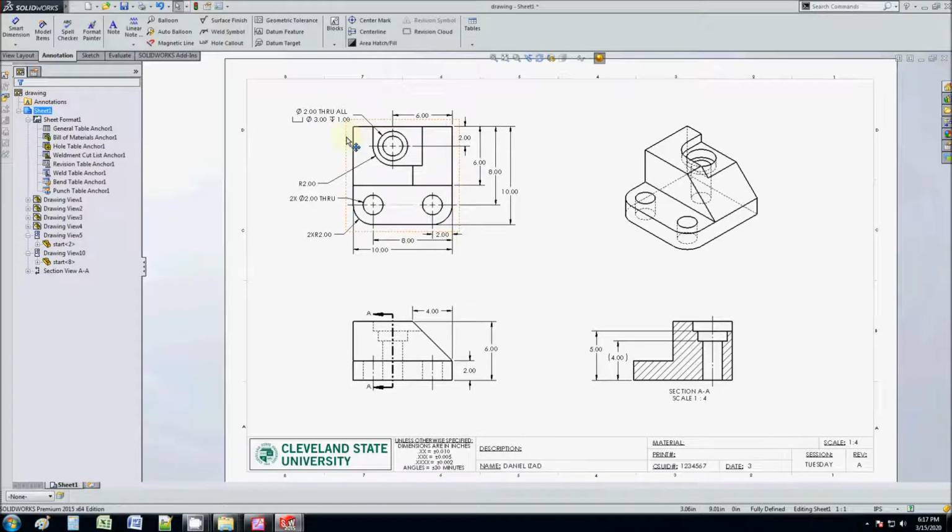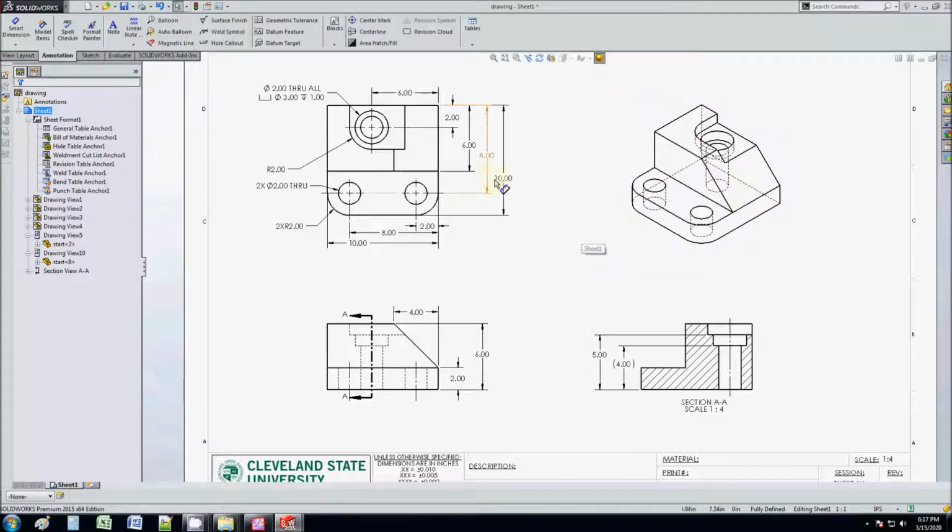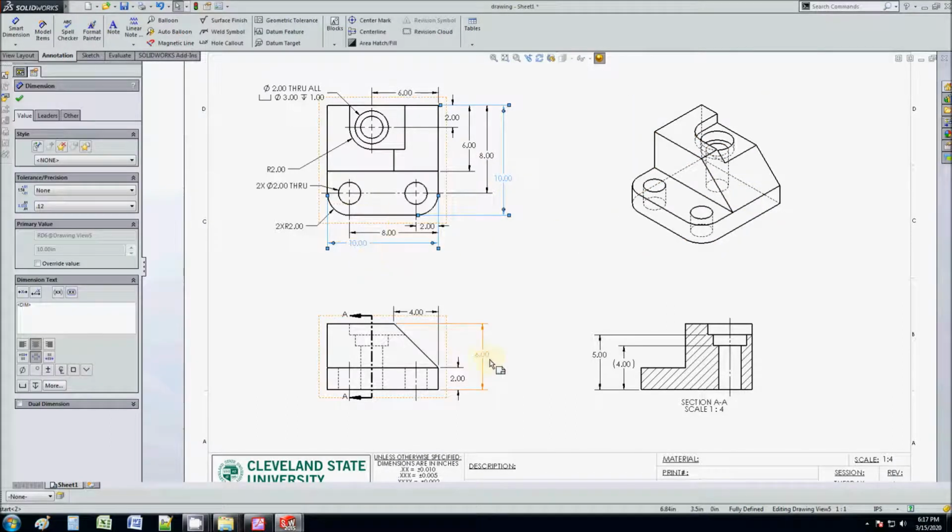Okay, so let's see if I'm missing any dimensions. I'm trying to build this object. I have the width, length, and height, and then I have this chamfer here. So it's going to cut this and there. Just cut the chamfer, and then let's see what else. We have 2 through holes here. I need to know the x and y position of those. And I know they're through, I know their diameter, so we're good. We got these. Then we need to know the size of the pocket. We know the center of the pocket and the fillet and how deep it is.